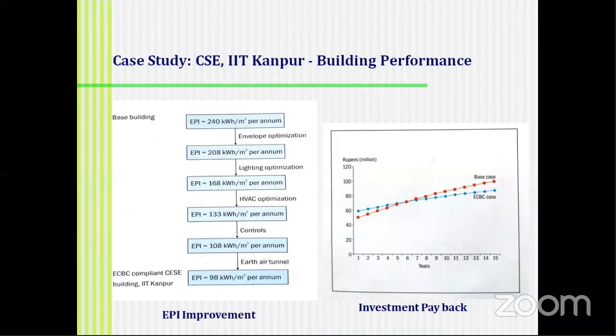In fact, lighting has always been targeted as the first criterion for energy efficiency in buildings because it brings significant differences, and at the same time it does not affect comfort, because we have what is known as the lux level. So very easily the lux levels can be managed using these energy efficient devices. At the work plane, the illumination levels can be ensured, including the daylight component that has to be integrated into this. So lighting has been one of the first criteria attempted for all certifications.